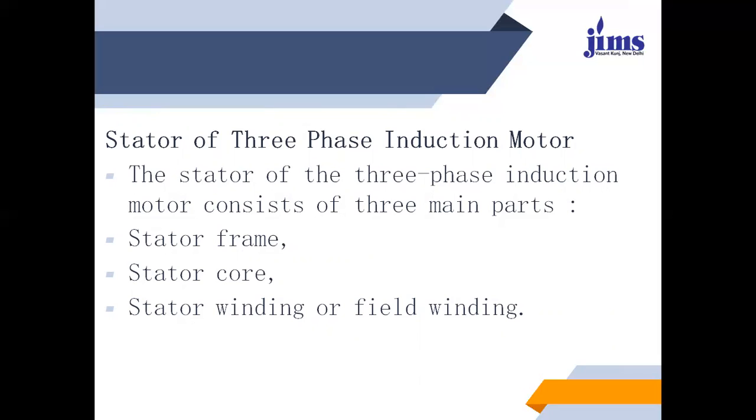In DC machines, we use the word field winding, but here we use the word stator winding because there is no excitation field. There is only an AC supply delivered to the stator of the machine, so we are not using the word field winding. It will develop a field, but in the DC machine the purpose of the field winding is to produce the field in a particular direction. Here, the winding works in both directions, giving a bidirectional movement.